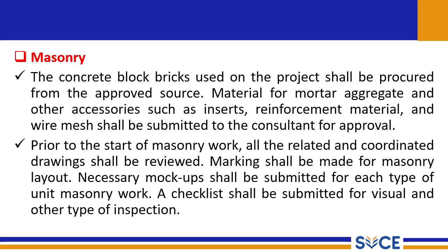Masonry. The concrete blocks and bricks used on the project shall be procured from an approved source. Material for mortar, aggregate and other accessories such as inserts, reinforcement material, and wire mesh shall be submitted to the consultant for approval. Prior to the start of masonry work, all the related and coordinated drawings shall be reviewed. Marking shall be made for the masonry layout. Necessary mock-ups shall be submitted for each type of unit masonry work. A checklist shall be submitted for visual and other types of inspection.